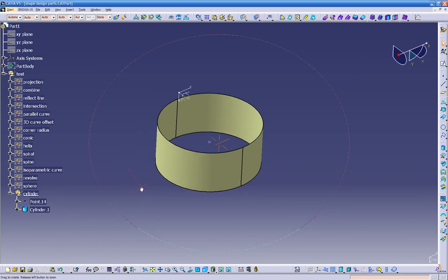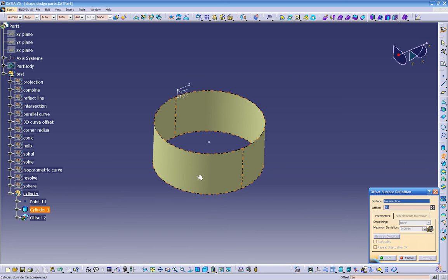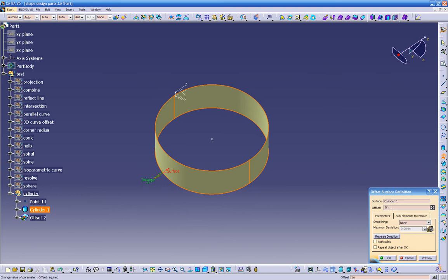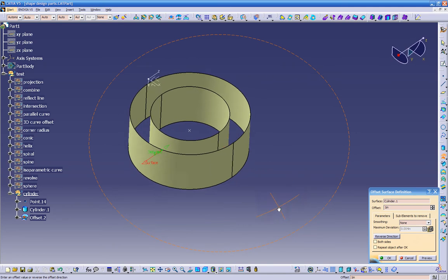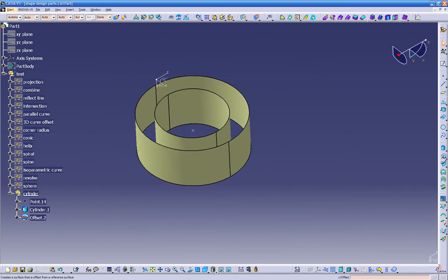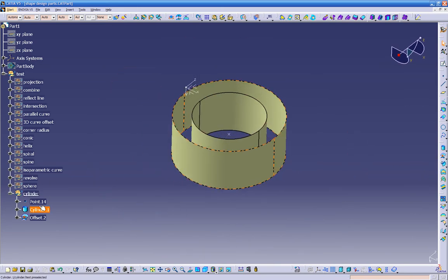Let's go to our next option. It's offset. Just click on any surface you want to offset, give it a dimension, and click preview or reverse. That's pretty self-explanatory. Same thing with this rough offset, works the same as this, and a variable offset works the same as this, but you can change the offsets. For example, if you have a pad over here to 1 inch and you offset this 2 inch, you can do it in the variable offset. Let's see if we can make a quick sample.